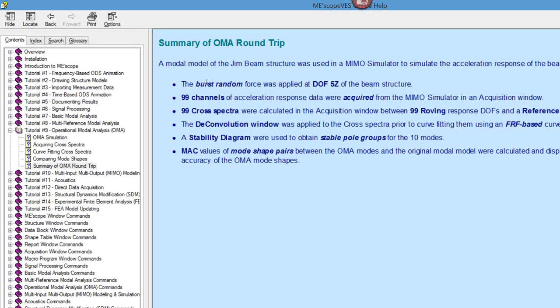The random excitation combined with spectrum averaging will remove the effects of any nonlinearities in the structure, and certainly something like a 747 we would assume is nonlinear. Modes are only defined for linear dynamics, so we want to average away the nonlinear effects and end up with measurements which show us the linear motion of the structure so that we can curve fit those measurements and get some mode shapes. So that's the whole idea behind burst random.